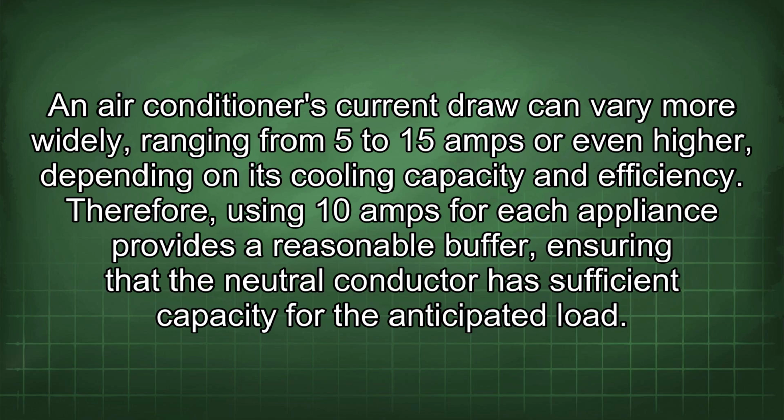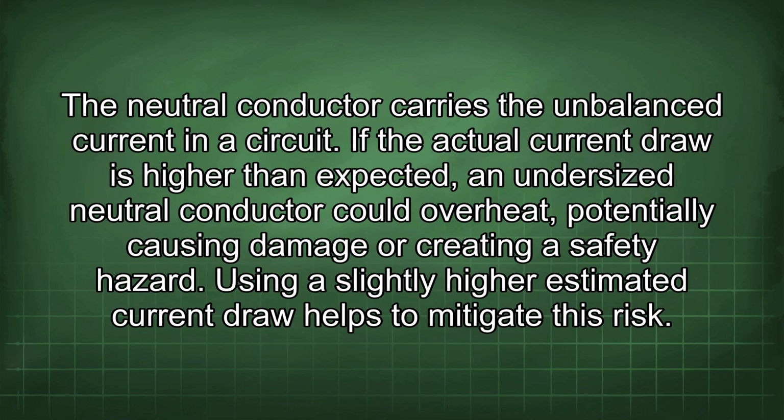the anticipated load. The neutral conductor carries the unbalanced current in a circuit. If the actual current draw is higher than expected, an undersized neutral conductor could overheat, potentially causing damage or creating a safety hazard. Using a slightly higher estimated current draw helps to mitigate this risk.